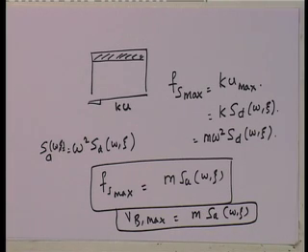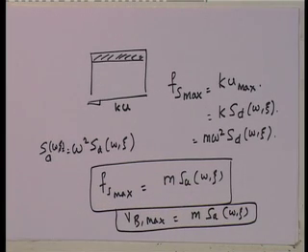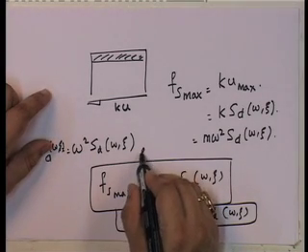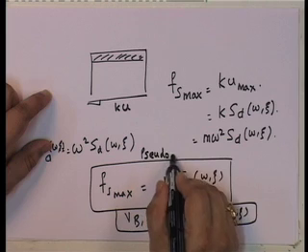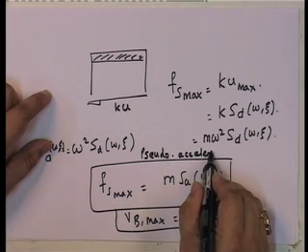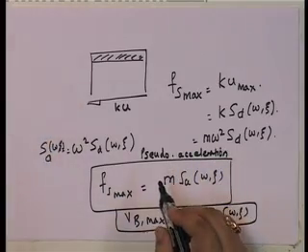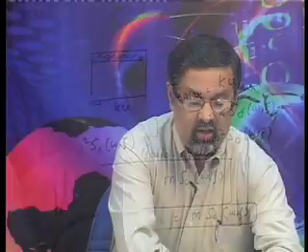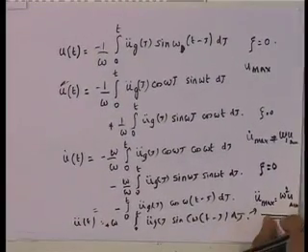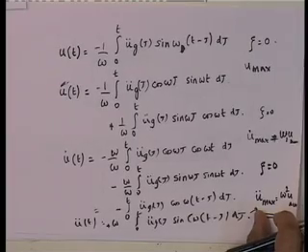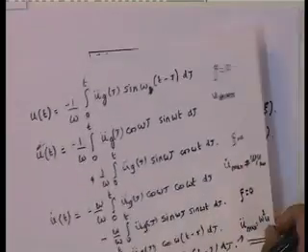Okay. So, what is this S a? The S a is related to the deformation spectrum, and in a way force is equal to mass into acceleration. So, it is like a pseudo acceleration, because it does not represent the true acceleration. The only case where it represents the true acceleration is, if you remember, we looked back at that particular function, didn't we? We looked back and we saw that when you have psi equal to 0, the peak u is equal to omega squared into d.